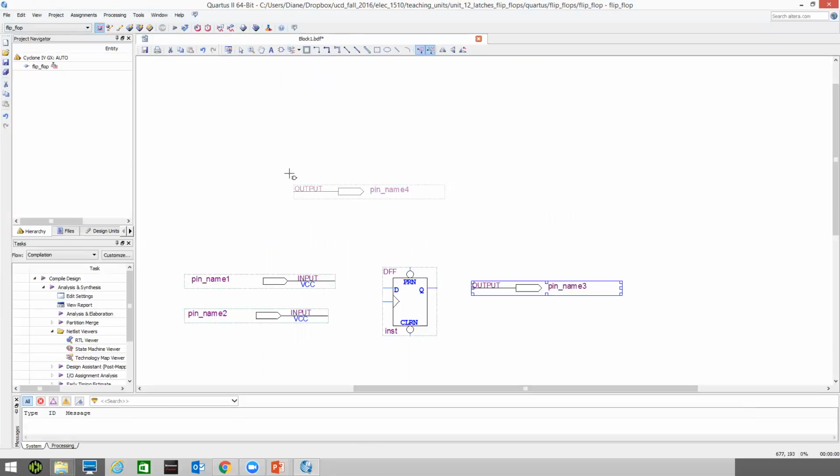What I'd like to do is physically wire this to the board. So I'm going to use SW0 because I'm using an Altera DE2 board. I'm going to use then KEY0, and key is the push button. Push button 0. So D will be whatever's on my switch. Push buttons are better to use for their edges than the switches. Switches, it's harder to detect the edge when you slide them back and forth. Push buttons are a little bit easier for you to know where the transition is. All right, and my output Q.